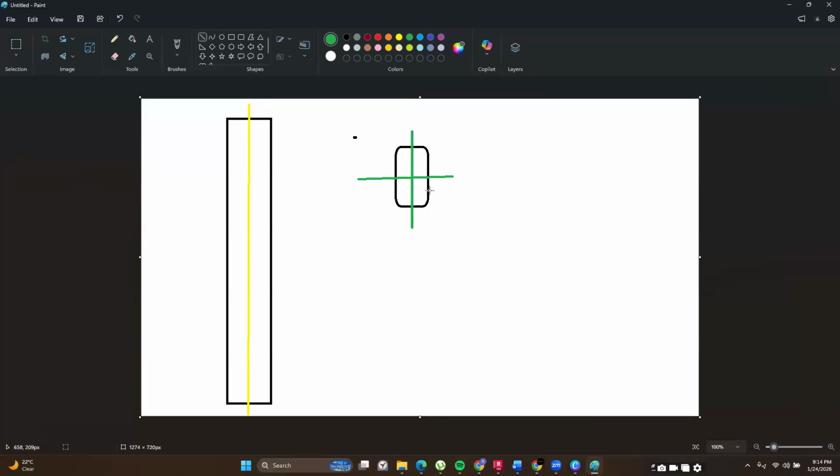All right. So from this, you can tell if this is the beam, the Fz is going to be your shear forces. And that is what you are going to be looking at when you are designing for the stirrups or when you want to place your stirrups. And then if the forces are in this direction, then you expect them to cause a bit of torsion on your member.